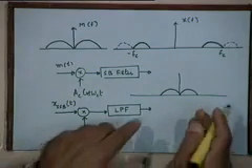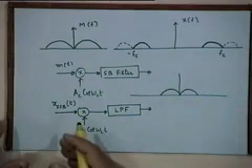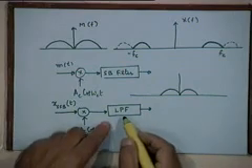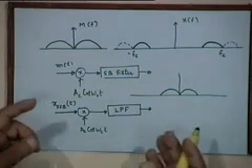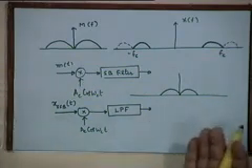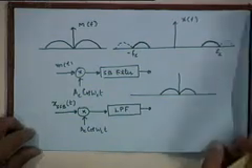Of course there will also be translation around 2fc and minus 2fc, but that will be eliminated by the low pass filter. So the reconstruction process in the time domain as well as in the frequency domain follows the same principle that we had for the case of DSB-SC, the double sideband suppressed carrier modulation.